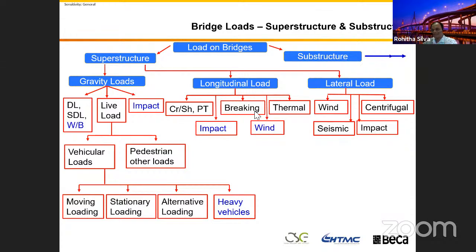And the braking, of course. While you are driving a car, you accelerate, decelerate, you stop on the bridge. Because of that, there is a braking effect all the time. When you brake the car, that inertia force is absorbed by the bridge, so the bridge needs to accommodate that. In addition to that, thermal effect, because you know that if you heat, it will expand. If the temperature drops, if it is cold, it will contract. So the expansion and contraction is in there.